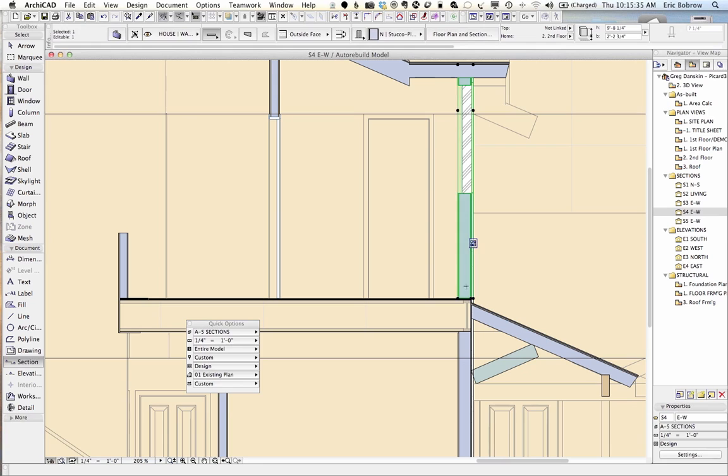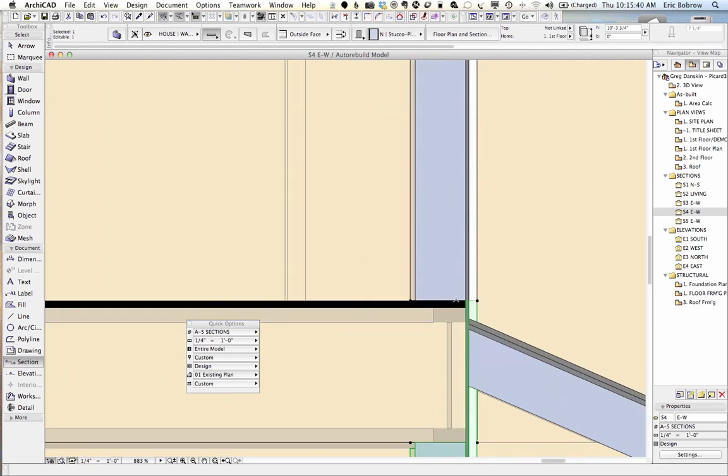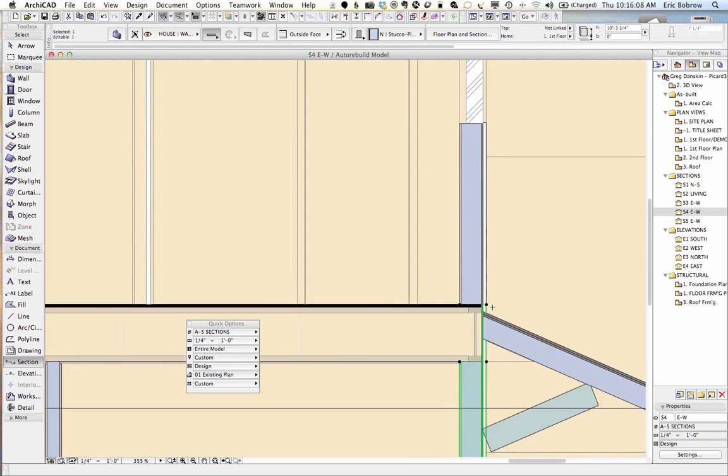I would say just leave the wall starting here and take this other wall up to it, and just make sure you're putting a composite going through, and the composite for the slab, for the structural, for the plywood, the structure, and the gypsum should go only out to the face of framing. That will allow the sheathing and the stucco to just sort of pass by without worrying about the priorities. Super.